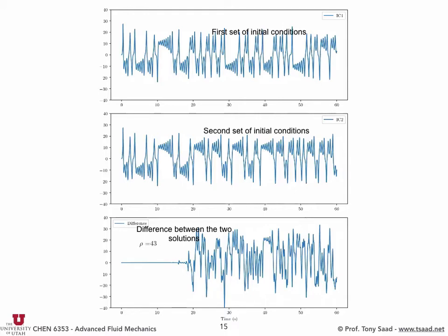Anyway, but you see, this is a silly dynamical system. It's nothing. It's a set of ODEs. Imagine adding so much complexity. But it's all fluid flows. Such a complex dynamical system of equations that is chaotic, and that's what we mean by chaos. Beyond a certain threshold of the Reynolds number, any slight perturbation in the flow is going to cause you to land on a different solution.